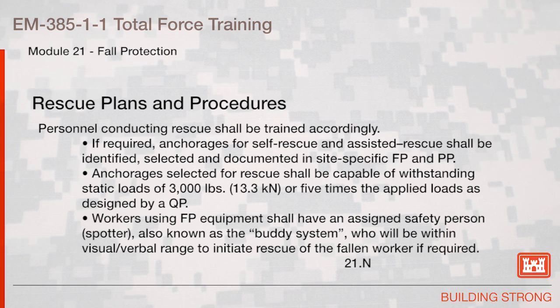Workers using fall protection equipment shall have an assigned safety person or spotter, also known as the buddy system, who will be within visual or verbal range to initiate rescue of the fallen worker if required.